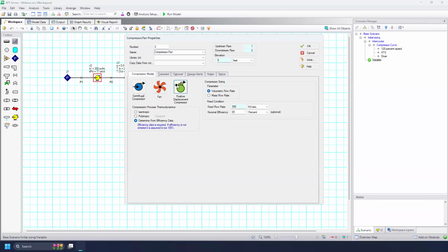But yeah, not the speed directly, but you could scale the flow rate itself, since it's going to be tied to the speed. I think that's essentially how you would do it, but it wouldn't be using the variable speed tab. It would just be setting this to, oh, this was supposed to be SCFM. Well, yeah, it would just be setting this to 600 if you wanted to double the speed or anything like that.